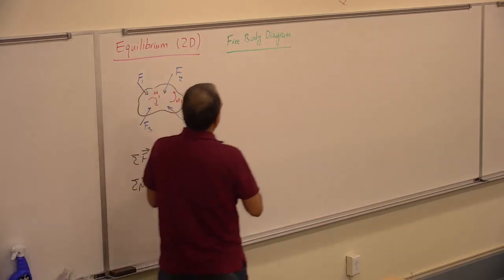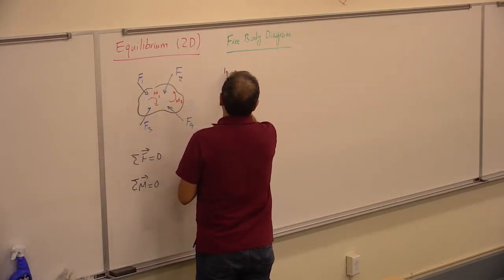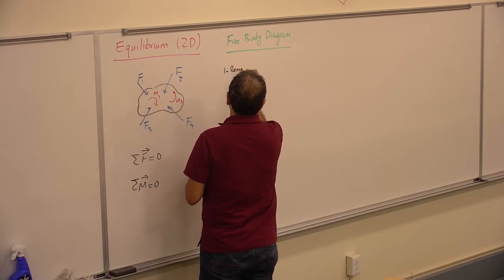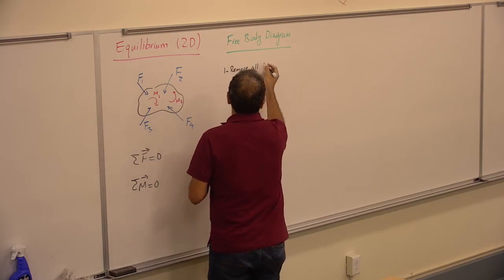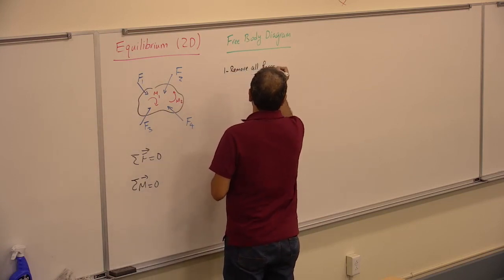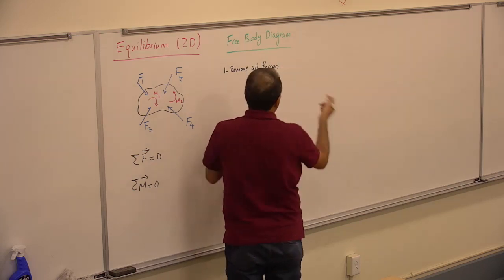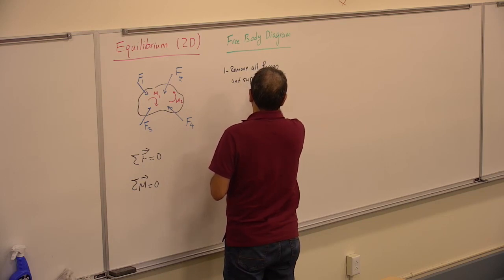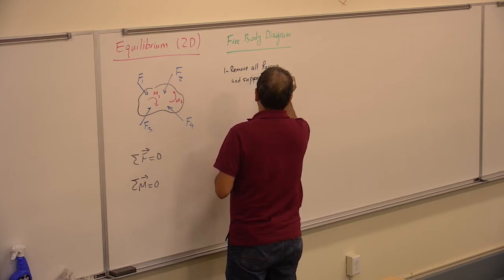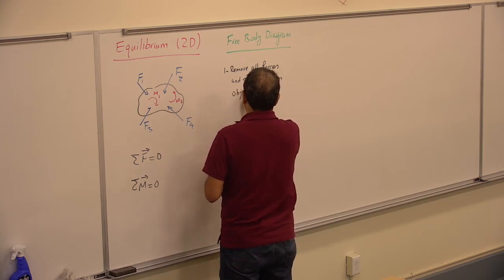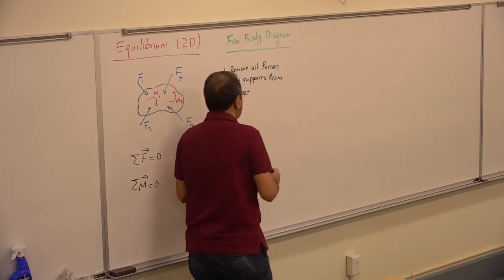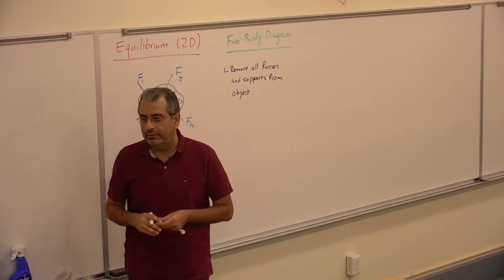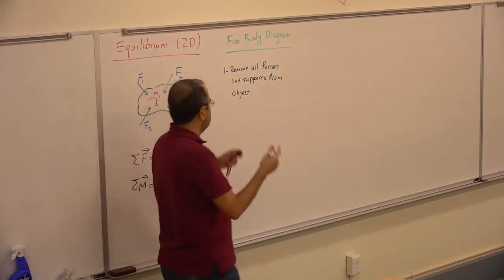So the first step is remove all forces and moments and supports from the object. In other words, isolate that object.